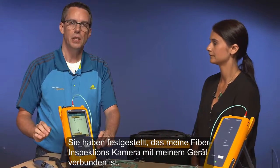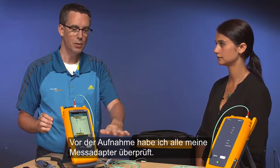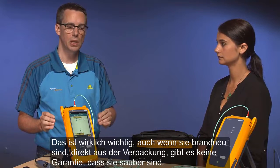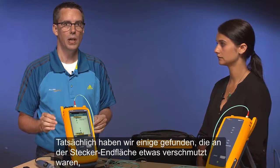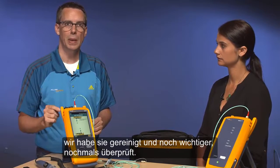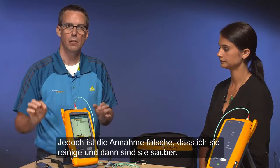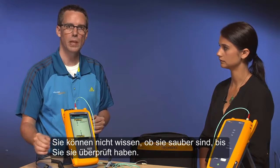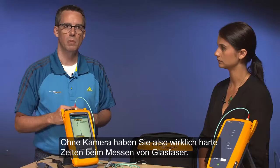Now you'll notice here that the fiber inspection camera is attached to my instrument. So off camera, before we started this, I went through and I inspected all of my test reference cords. That's very important to do because even though they're brand new out of the bag, that's no guarantee that they're clean. In fact, we did find a couple of them were a little bit dirty on the end faces, and we cleaned them, and more importantly, we inspected them again. You can clean them using these one-click pens, but the false assumption there is that once I clean it, it's cleaned. You don't know it's clean until you've inspected it. So without a camera, you're going to have a pretty rough time doing your fiber optic measurements.